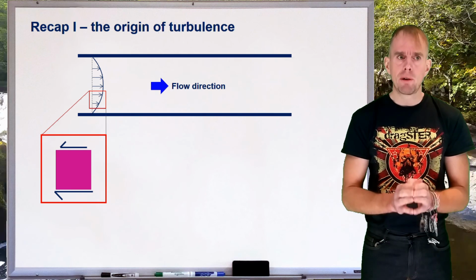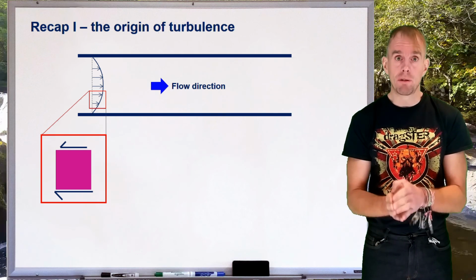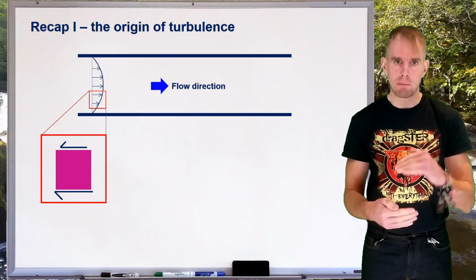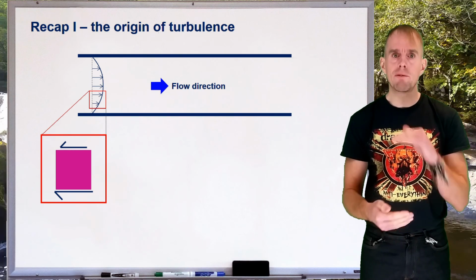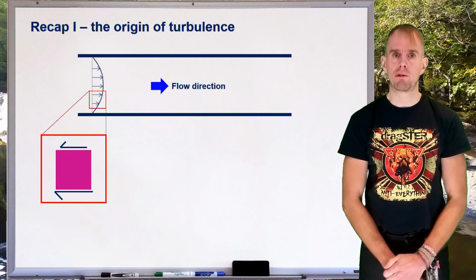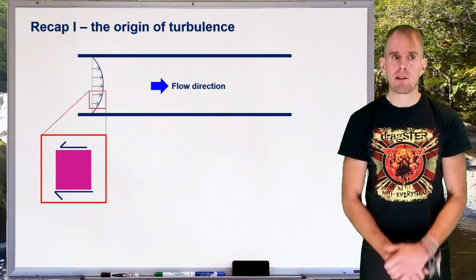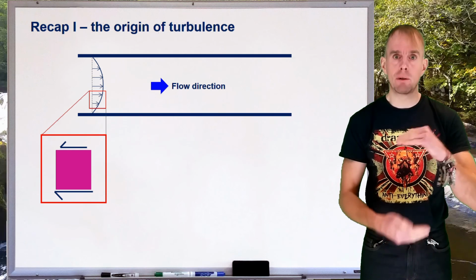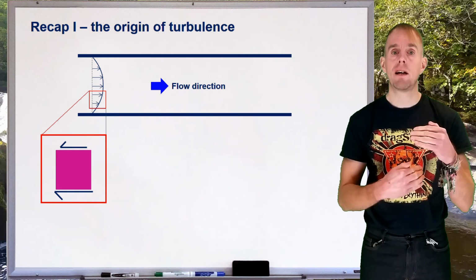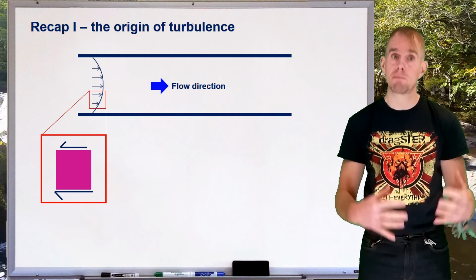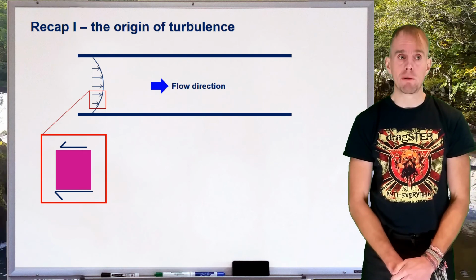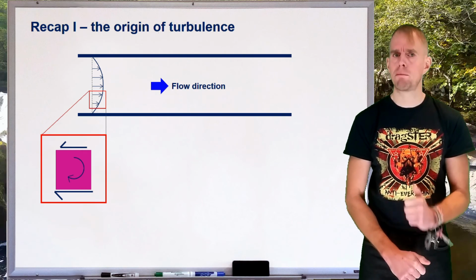Because our element of fluid doesn't sit on the symmetry line equally top and bottom, we have an asymmetric set of shear forces acting on the upper and lower surface. And you will expect, if there's shear on the upper and lower surface imbalanced, that there will be a net moment as well to counterbalance that. And so that's what we find. And this is an important point.